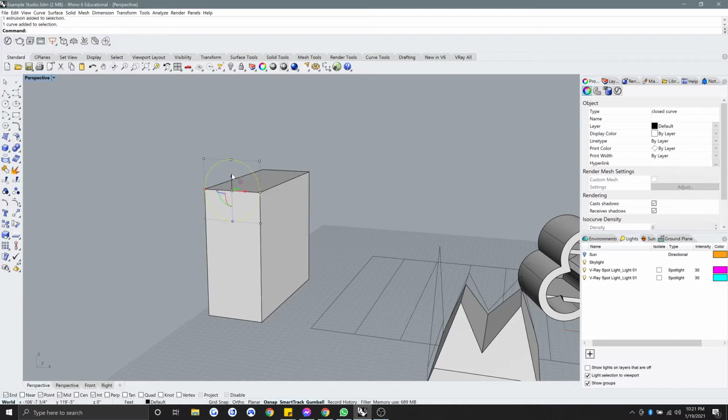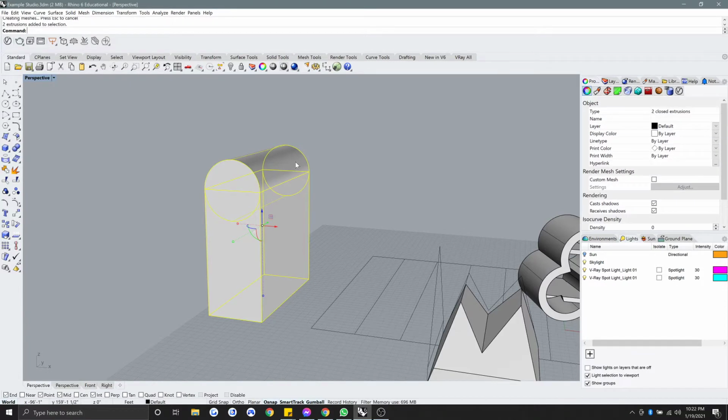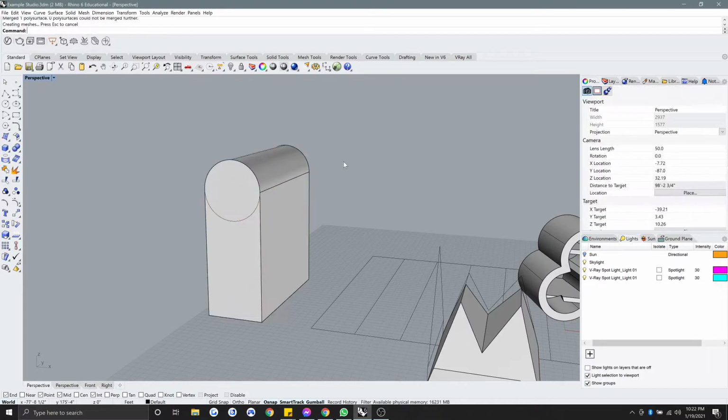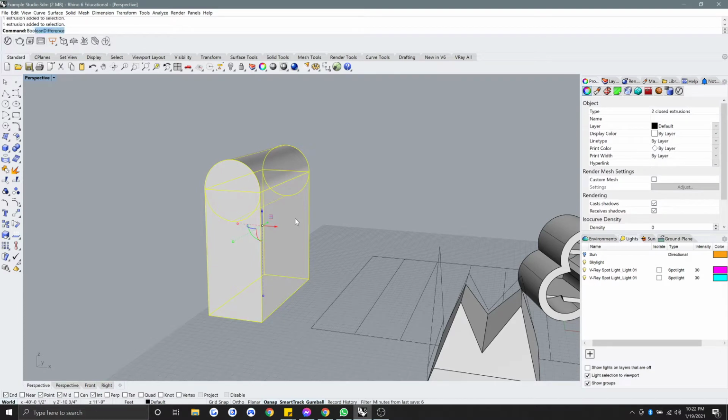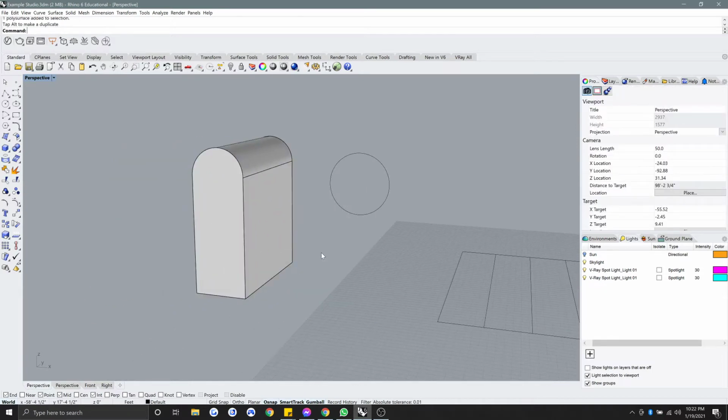And I could take the time to bring this down here, slice off these corners, and that would give me my semicircular top to this. But what I'll do instead is I'll extrude this curve all the way to here, and then I type MH. That's a shortcut for me. You guys can Google how to set shortcuts in Rhino, but all I'm doing is selecting my two objects that are separate and essentially typing Boolean union, and then typing merge all faces, which gets rid of that line that runs across there, and I just have a shortcut that does those two things in combination.